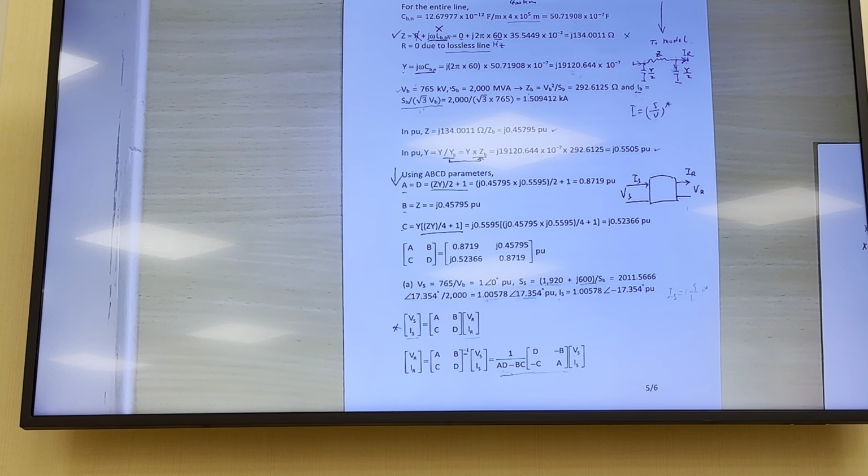That is the interesting part. You must understand that the relationship between Y and Z is the reciprocal. We have ZB. Now what is the YB? YB is just 1 over ZB. Then Y over YB equals Y times ZB. That is a key point. You have to understand.